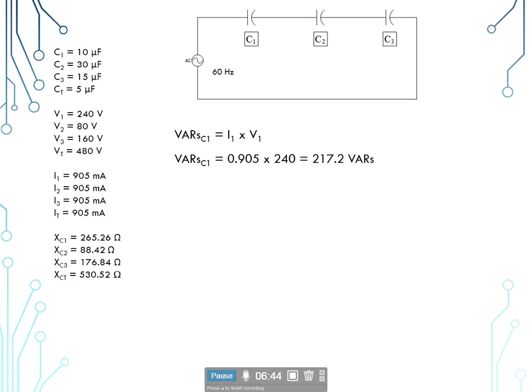And I might add that when we're in AC, we always operate off of RMS values for our voltages, our currents, and our power. RMS voltage, root mean square, is simply 70.7% of our peak AC voltage. That's what we use to make these formulas work, because if we had 100 volts AC or 100 volts DC, it would take 70.7 volts AC to produce the same amount of heat in a resistor that 100 volts DC did. That's why we are able to use these same formulas with a little bit of a variation.